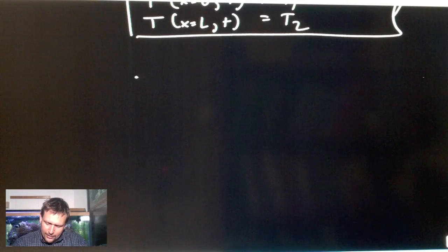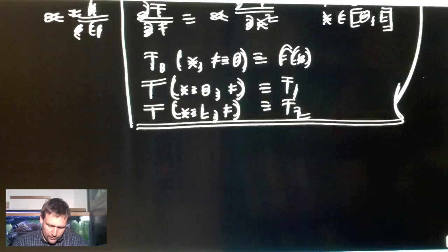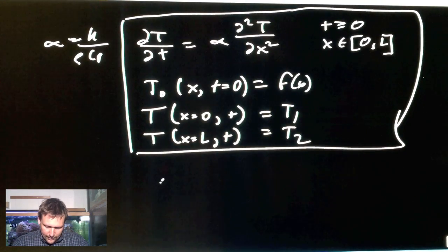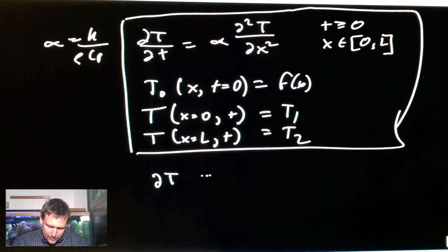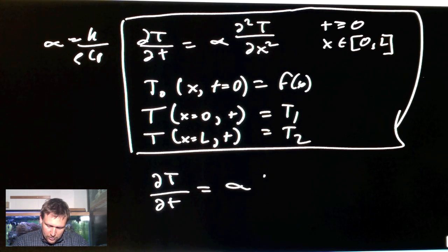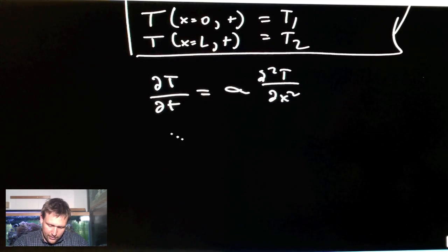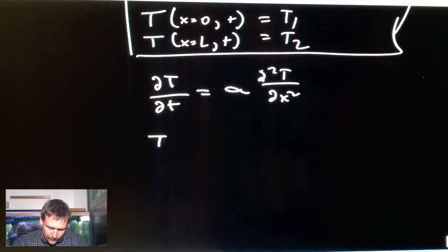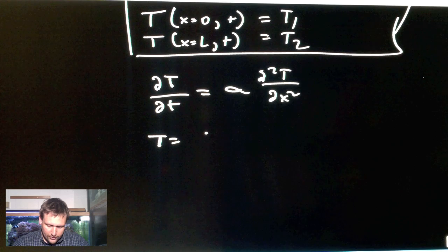I think the best way to begin the process of defining the dimensionless groups of a problem is to write down the equation, first the differential equation here, alpha del squared T by del x squared, and make a list of the units that are associated with each variable.